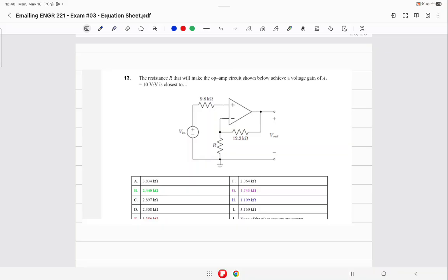No? Okay. What's this voltage here? Is it just VN? Is it because I positive is 0? Yes, always the current going into the terminals of the op amp is 0. So what is this voltage? VN.